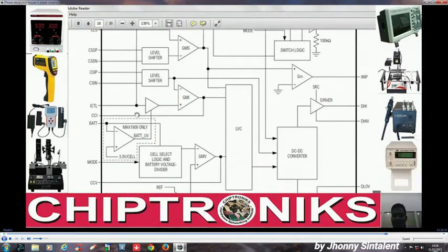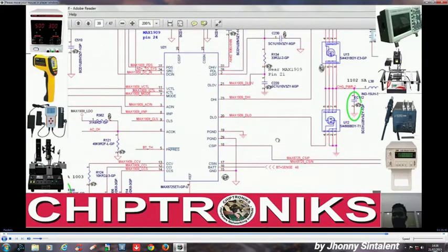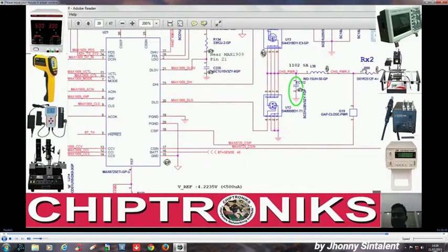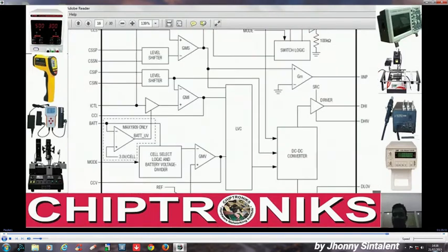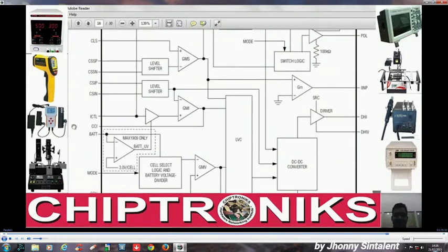This is coming from the IO controller, and this is CSIP, CSIN. You can see in the schematic diagram what CSIP is. CSIP is this positive side, this is the negative side. It is sensing the output current, and the input ICTL is the value given by the IO controller, and CSIP and CSIN is the value that it actually senses. It is going to a level register.